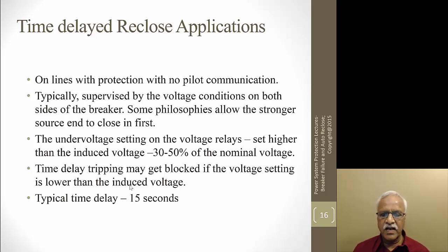The typical time delay is set to about 15 seconds. 15 seconds is the duty cycle of most breakers. If it opens and closes, you give 15 seconds before you open again. Open, close, open is one duty cycle of a breaker.